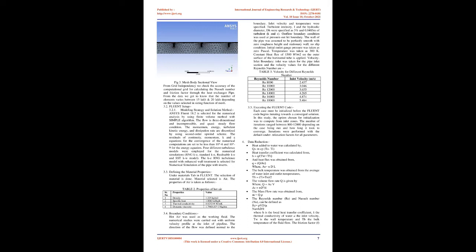Friction factor, a dimensionless parameter, F, is written as friction factor, F, equals (ΔP/L)/D, 1/2 * ρV². Where ΔP equals pressure drop across test section, Pa.